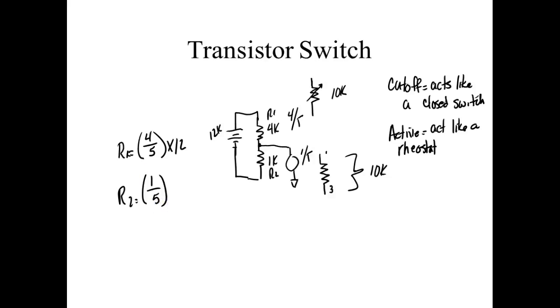So with the voltage divider formula, you can calculate the voltage drop in a series circuit without calculating current. Because the resistor will drop a voltage relative to the other resistors in the circuit. And that ratio will always be the same, which is neat.